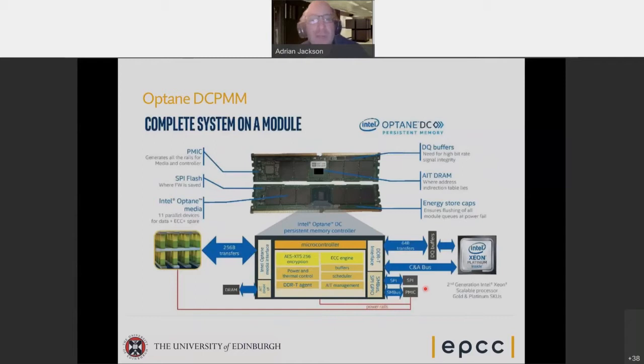challenges. As I've already mentioned, the kind of persistent memory we have available at the moment is a form of memory from Intel called Optane DCPMM. What's transformative about it from a memory point of view is that it comes as persistent memory, so you can store data long term, but it sits inside the same memory channels as your normal volatile memory. That means you can access it in different ways than if you were to write a file or read data from a file. You can access it as if it was just memory, and read and write chunks of data to it using standard programming techniques.